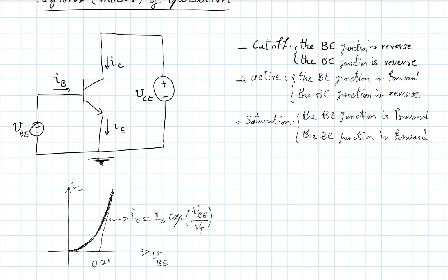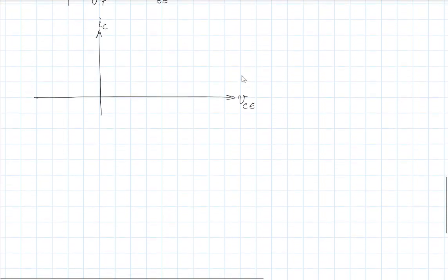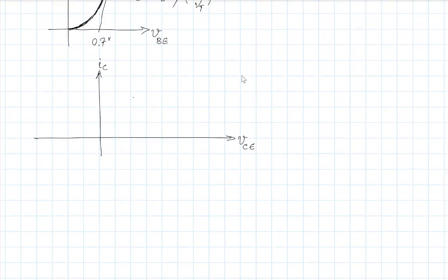Now, that was a controlled current source, so it was being controlled by some other voltage somewhere else. But its own voltage, so the voltage applied to the collector, should not, to first order, affect the current of that current source. And that's why we saw that the characteristics looked essentially flat for a range of things. And then eventually, if your VCE became very small, eventually you reach the point when things turned off. And we call this region saturation.